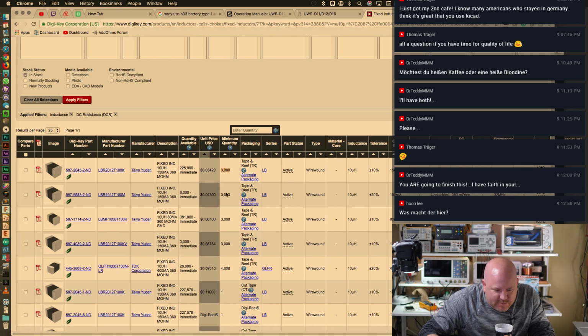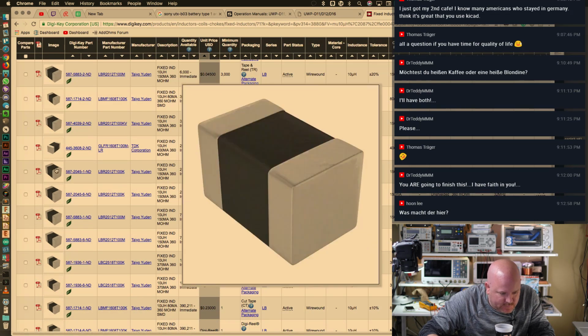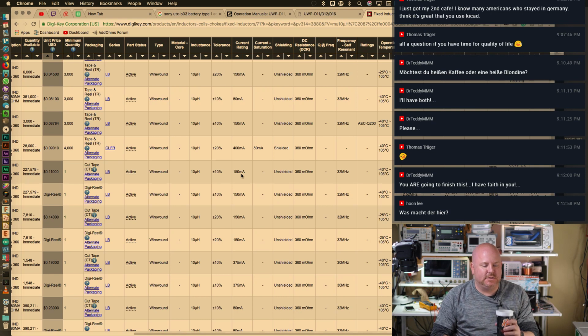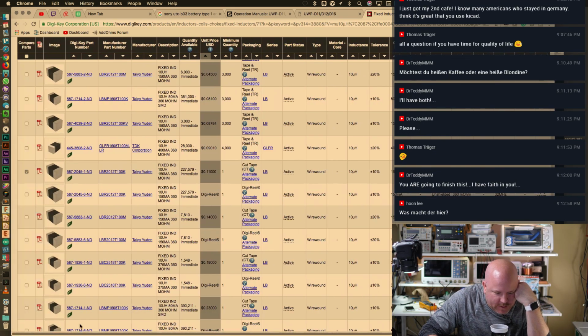All right. Oh, come on. Really? 2012. So it should be this one, right? That's not what I have already. Okay, whatever. 360, 10 microhenry, current 150 milliamp. Yeah, that's fine. I'm only going to be drawing 50. Okay. Wire round. And it's like 5 cents cheaper than the other one I had.